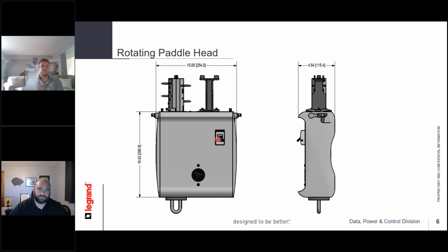We don't have to worry about swing space with this bus plug anymore. It goes straight up into the busway, because if you look at this, see how our stabs face the front and back of the box? In this photo here, our stabs face the sides of the box. So this thing goes right up into the busway how you see it.